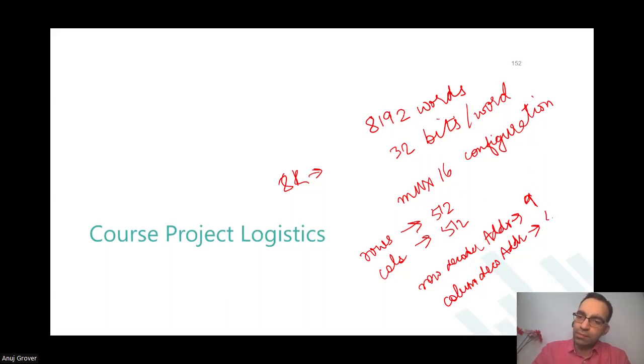So how many address bits are going to the decoder, the column decoder? 4. Does this match with the requirement of mux 16? To decode mux 16 we need 4. Yes. This is the memory instance that we will design as a class.